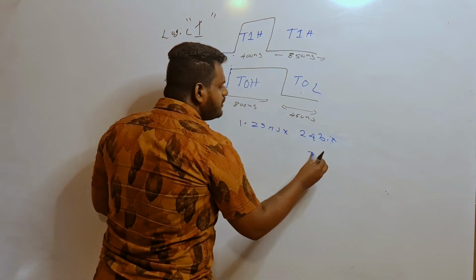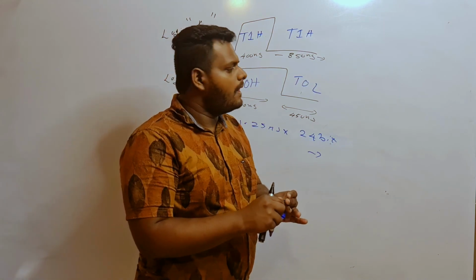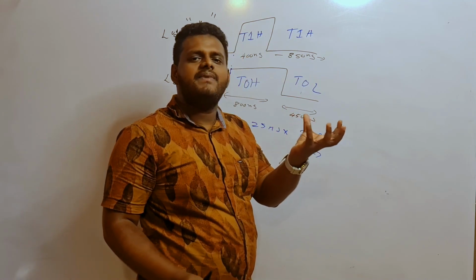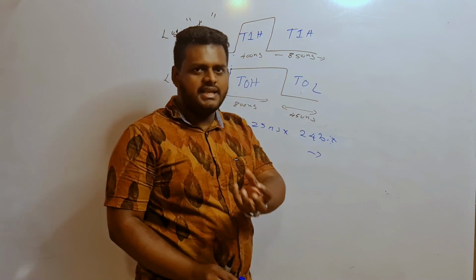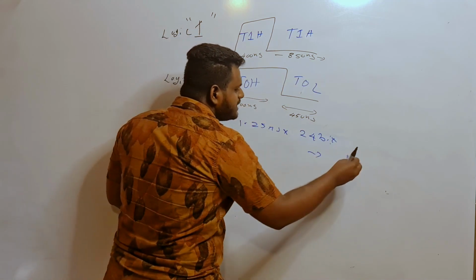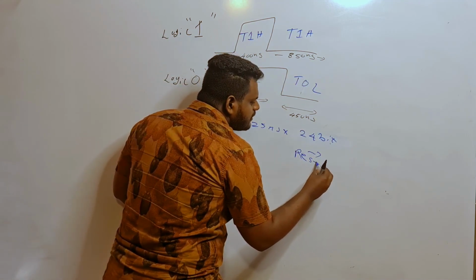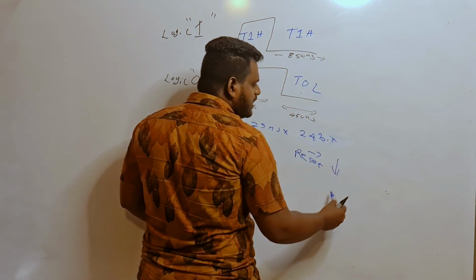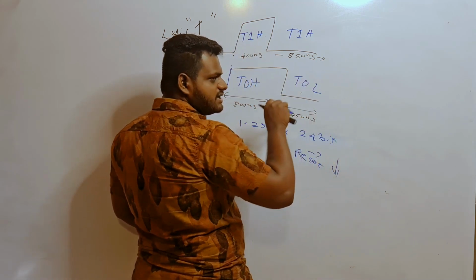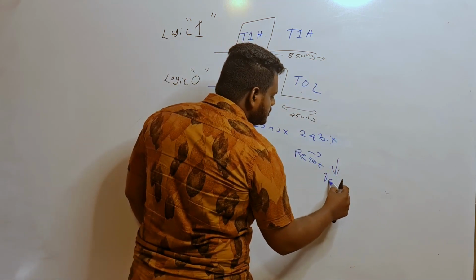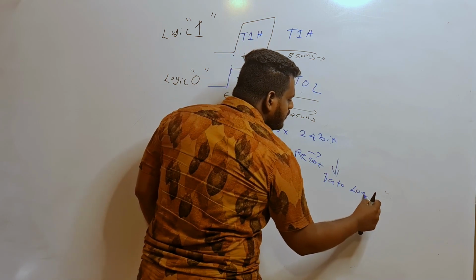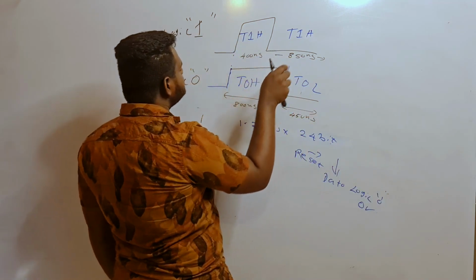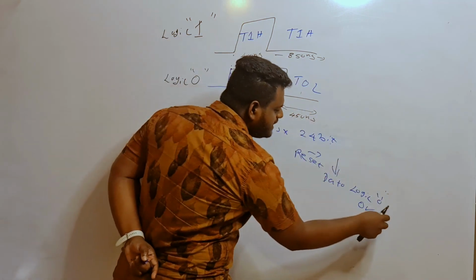After this, if you want to stop the bus, or light up that data value in any other pixel, they're talking about the reset timing. You have to put your data pin to logic 0, that means exactly 0 volts, not the other logic, only logic 0.